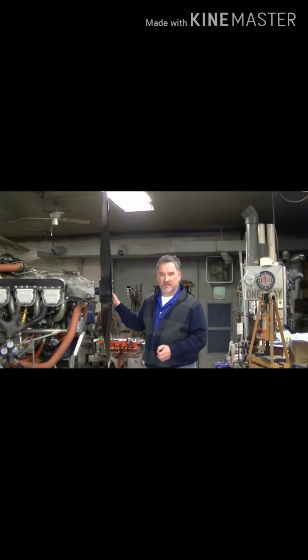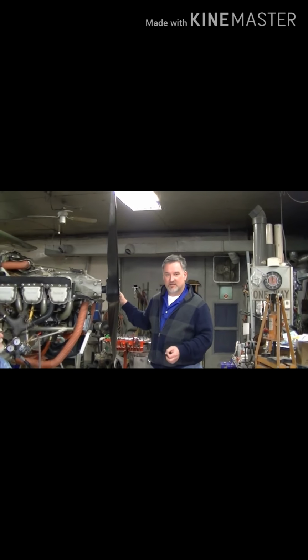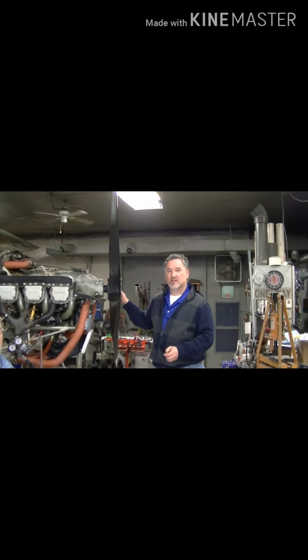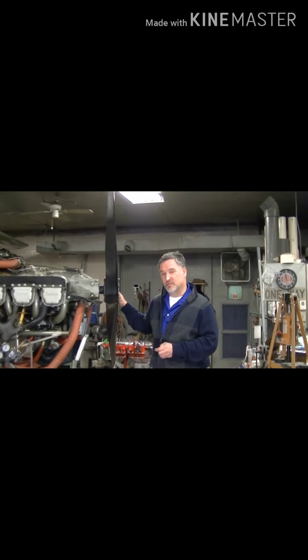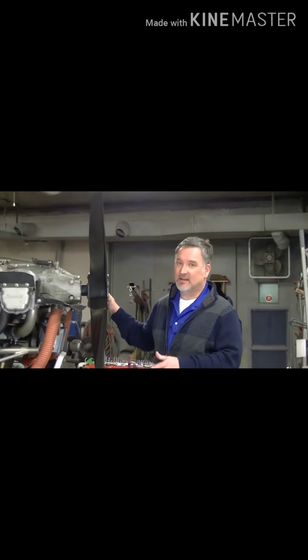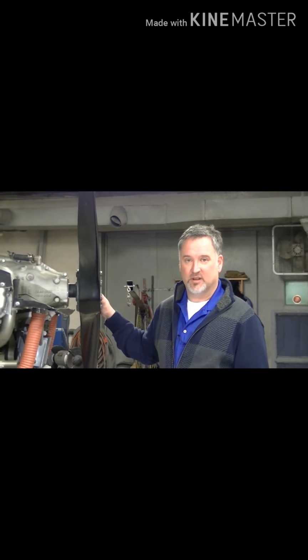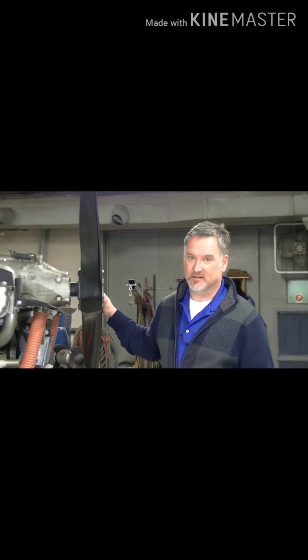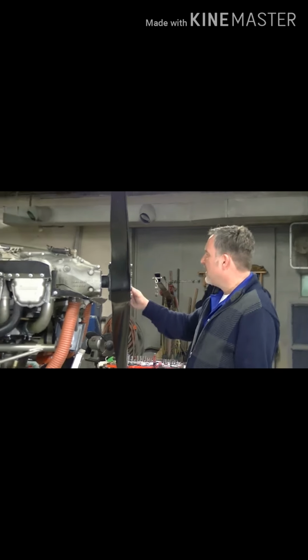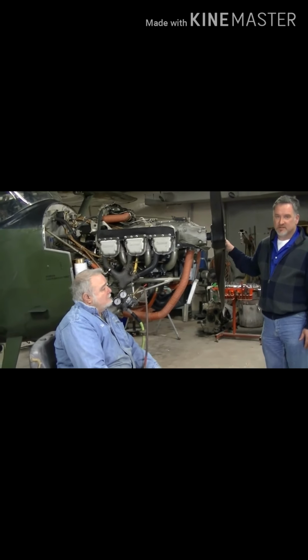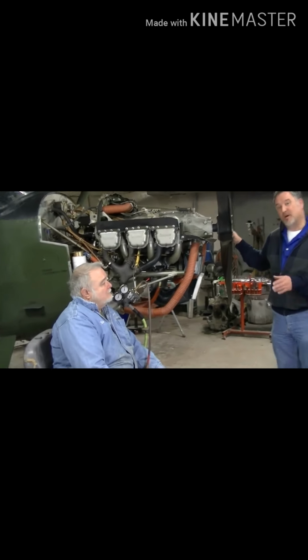Secondly, you want to make sure the aircraft is secured, the master switch is off, throttles and mixture control are closed, and remove the spark plug wires from the spark plugs themselves. Anytime you're operating near the engine, always remain outside of the arc of the propeller so you don't get hurt, basically. Safety first. The equipment needed is a differential compression tester set to 80 psi and a soapy bubble solution.